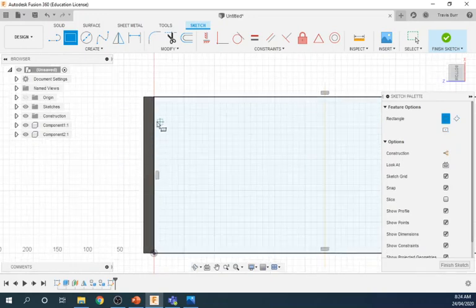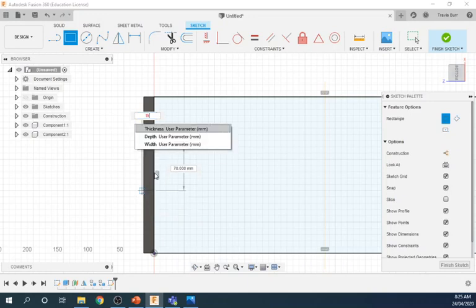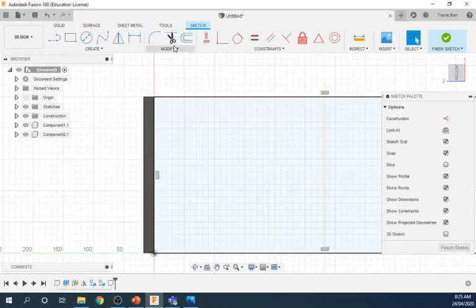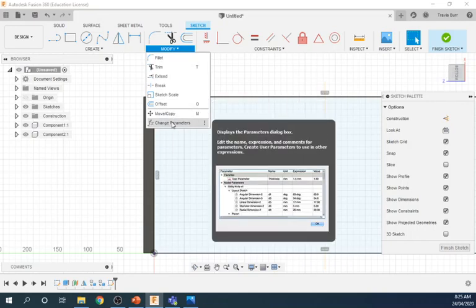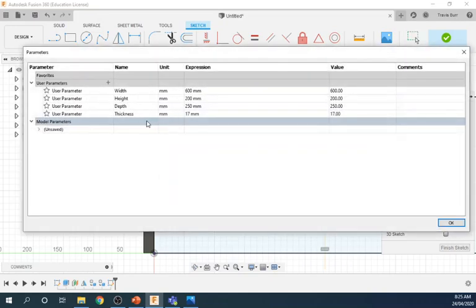Now with this, we need a couple teeth in here for this to hold into place. So I'm just going to come down and draw a tooth into place. So this would be thickness. And then our other one, I could do another parameter for this tooth, which is actually a good idea. So I'm just going to go escape here, modify, change a parameter, because we want quite a few teeth in this.